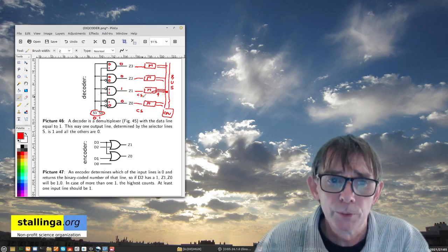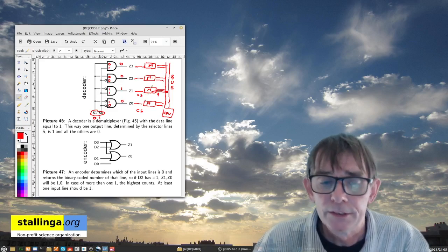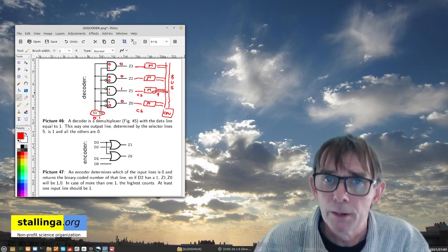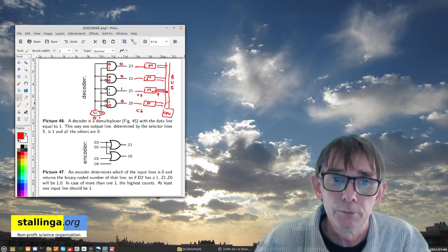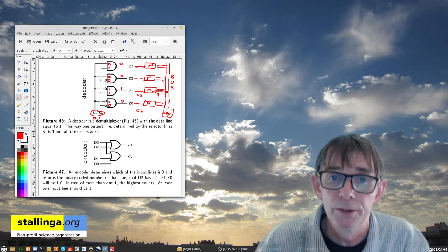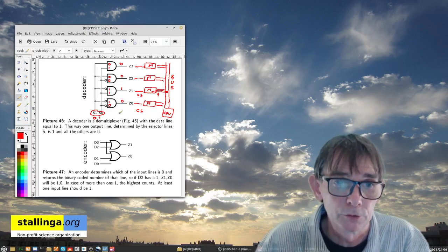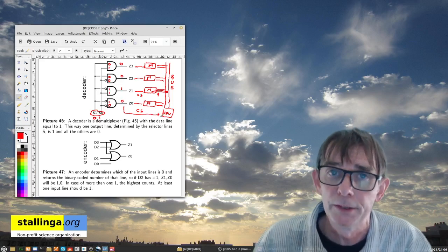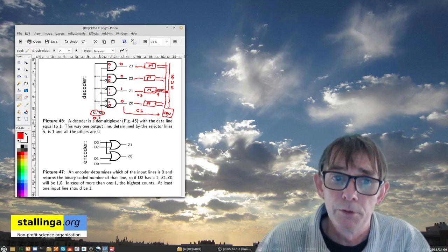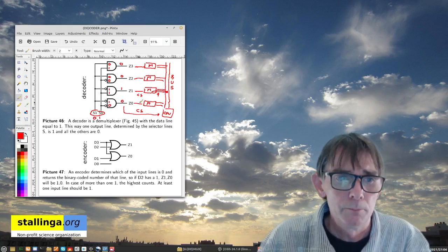And with this chip select, we can activate and deactivate a chip, and one of them can be put into talker mode and place its contents on the communication bus, and then the CPU in that case can be listening. Or one of those can be actually connected to the CPU, and can also be placed in talker mode, namely when it wants to write to memory.